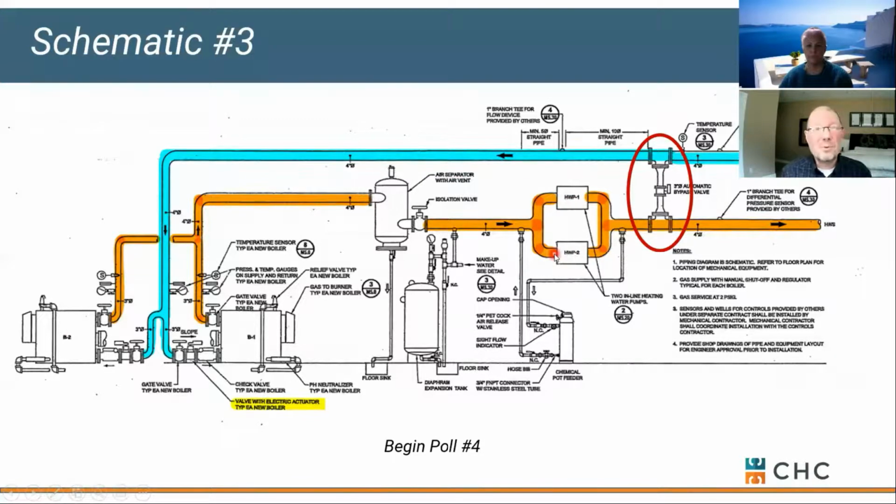So how do you resolve that? Well, one option is to put a bypass in the mechanical room, okay? So if flows become too low in the system, now you open up this bypass, you send some hot water leaving the pumps right back into the return of the boilers. That's an option. You have to write a very complicated sequence of ops to make that happen, but it's possible if you have a flow meter and you set your parameters correctly, okay? But again, by highlighting this drawing, a few things stand out, and as you start moving across, you're like, oh, wait a minute, what are we doing with this piece of pipe? Strikes up some conversation.